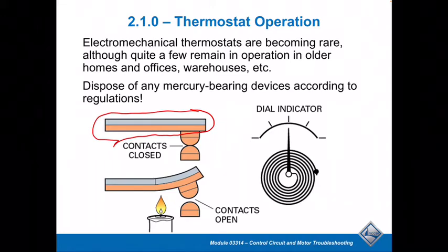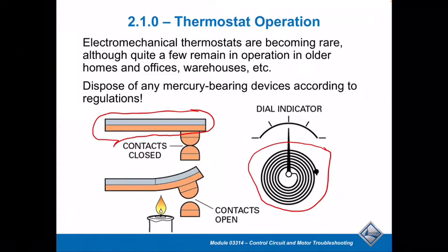When you think about the old round Honeywell T87 thermostat that was used for many, many years and is still in use in some applications, they have an actual wire wound or spiral wound bimetal. That bimetal just moves and shifts predictably based on temp.